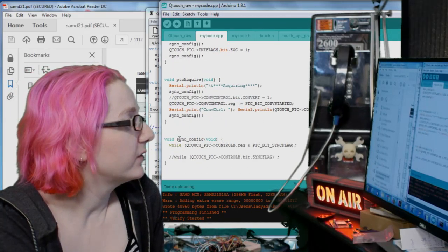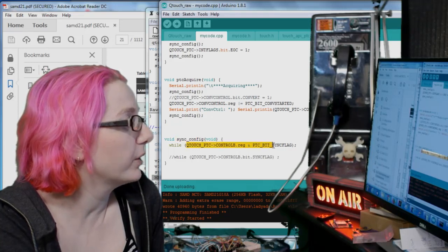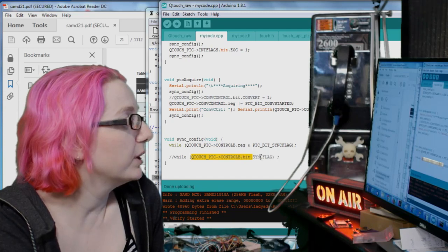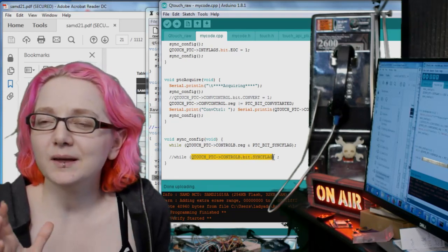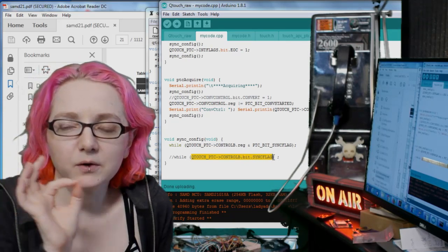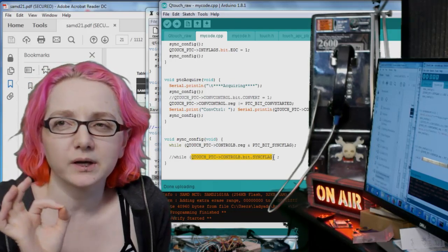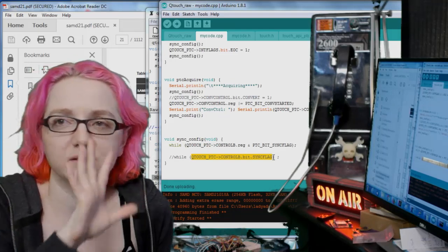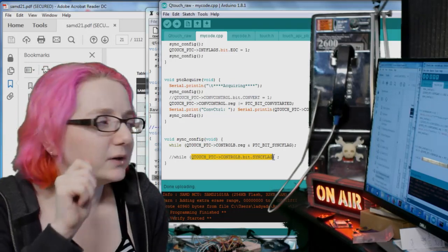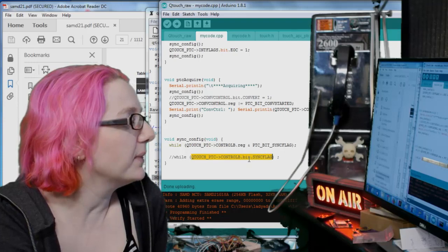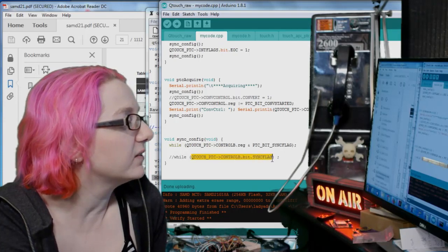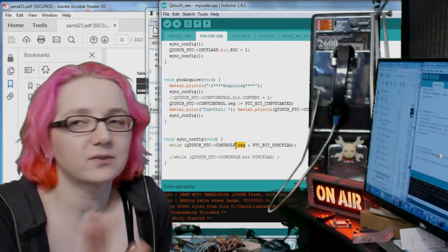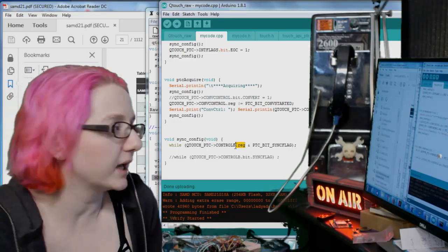For stuff like the sync config, you can read the whole register and AND it, or you can read the bit location. For reasons I'm not exactly sure, my bit location addressing isn't working, and I think there's just some detail I'm missing about setting it to volatile or some little twiddle I'm not doing quite right. So I'm not able to use this style where I actually address each bit. Instead, I have to access the register. I don't know. I'll take a look at it later.